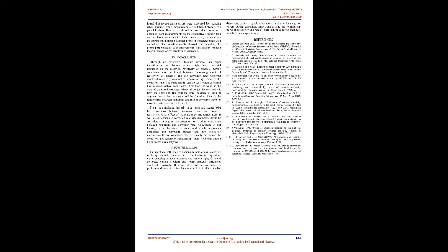This difference can be explained by the saturation degree of the sample. The results recommend that storing a sample underwater in the lab may cause a remarkably different degree of hydration than what may occur in a field structure. The sample that was continually saturated and the sample that was sealed and saturated at the time of testing had a similar resistivity for the same degree of hydration. However, the continually saturated sample had a higher degree of hydration at the same age.